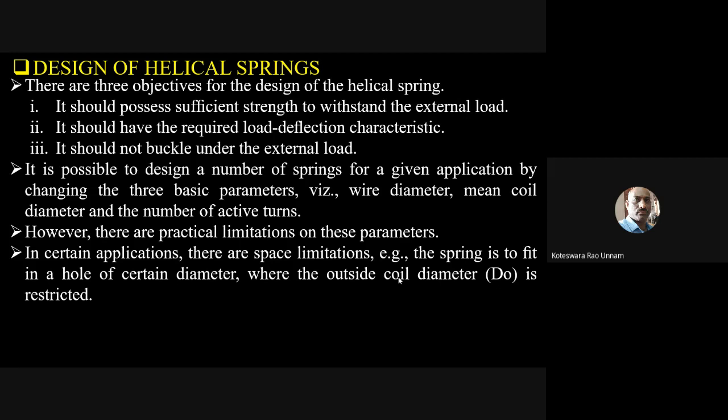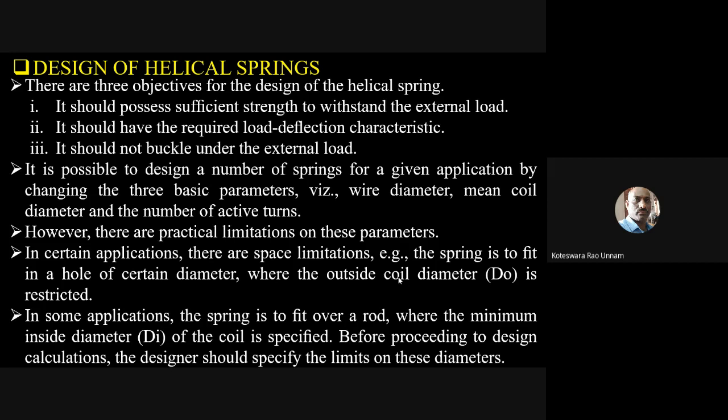So there is a restriction on the inside diameter of the spring also. That means where you have a certain application where you want to insert the spring into a rod, a rod is nothing but here in our example a refill. So refill is a kind of a rod. Then in that application you have a restriction on inside diameter. If in your application the requirement is to insert a spring into a hole, then there is a restriction on outside diameter, or in some other application where I want to insert the spring into a rod, then there is a restriction on inside diameter. So that is what I have written here.